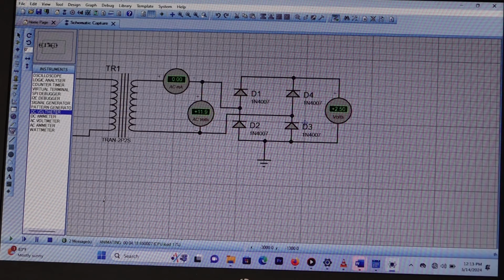Okay. So why do we have 2.51 volts? The answer is simple. Remember that 16.97 volts is AC, alternating current. It's the maximum voltage of the alternating voltage which has been supplied to the bridge rectifier unit. So finally at the output you have 2.5 volts, which is DC. So how about the remaining? Simple. The remaining maybe is AC components. Are we together?